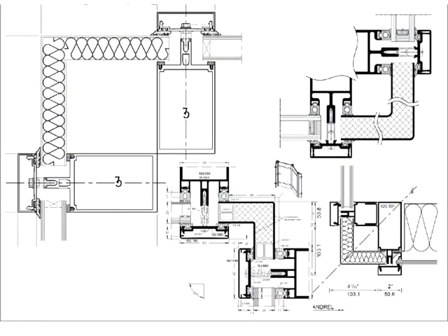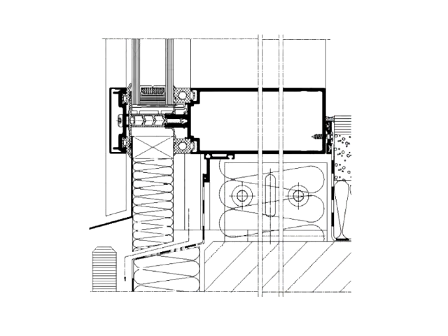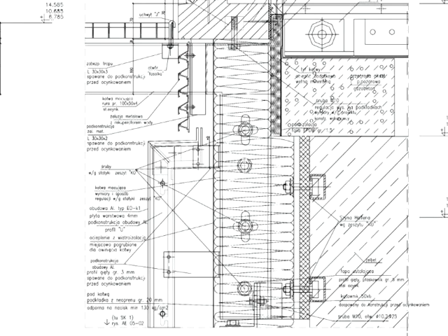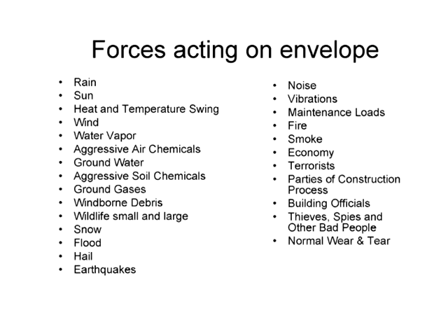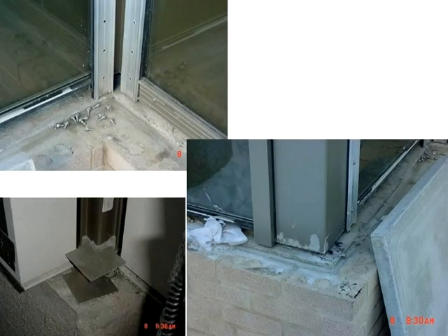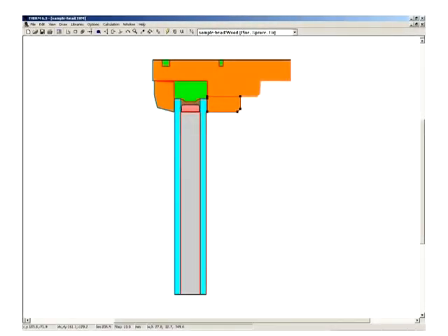You will need to coordinate horizontal and vertical details so they can actually work together. At this stage, your main goal is to verify whether the depth of assemblies and their interfaces would agree with the modulation and spacing of facade that you envisioned. Requirements such as heat, noise and fire resistance may easily require changes to the slab edges, distances, structural sizes and so on.